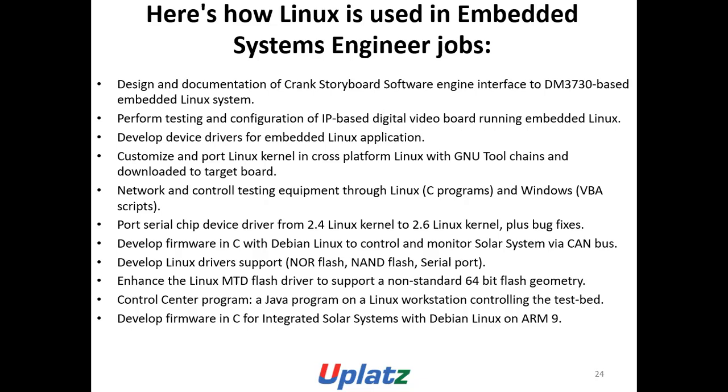Design and documentation of Crank storyboard software engine interface to DM3730 based embedded Linux system. Perform testing and configuration of IP-based digital video board running embedded Linux. Develop device drivers for embedded Linux application. Customize and port Linux kernel in cross-platform Linux with GNU tool chains and download it to target board.